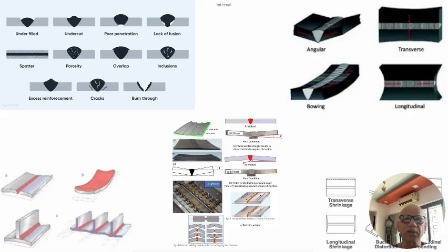These are all the different techniques, and it doesn't happen only in butt joints. You can see here it happens in fillets also, and how bad the fillets will turn. Both the vertical rib as well as the base on which you are welding the rib may have distortions, and that is not acceptable at all.